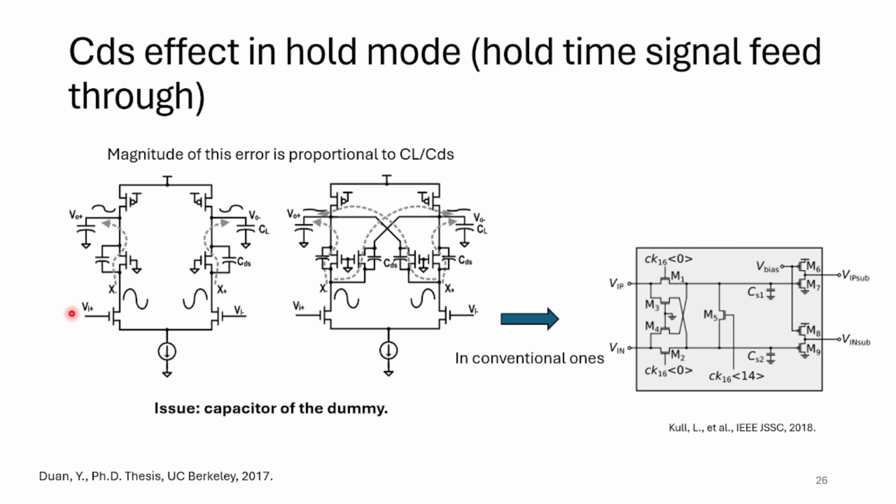Also, there is another matter which is mostly about the hold time. In the hold time, maybe the signal adds to your sample because of parasitic coupling. So you can add dummies, and because it's differential with two phases, when this one goes there, the one in the opposite phase comes here and removes the effect. Same as for here. The problem is if you add this and you want very high speed switching, this adds parasitic to your output in your tracking time.